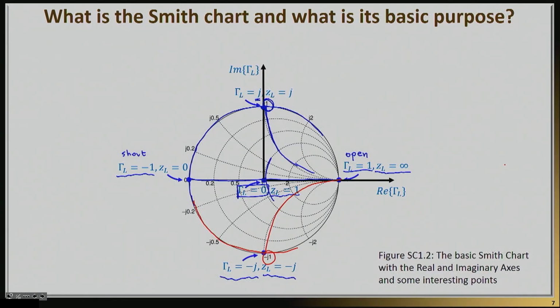So what I'm doing on all of these points over and over again is I'm putting essentially a point on the Smith chart, and then I'm reading the two families of circles to find out what load corresponds to that point. And since this is the real and imaginary part of gamma, I can also read immediately what is gamma L.